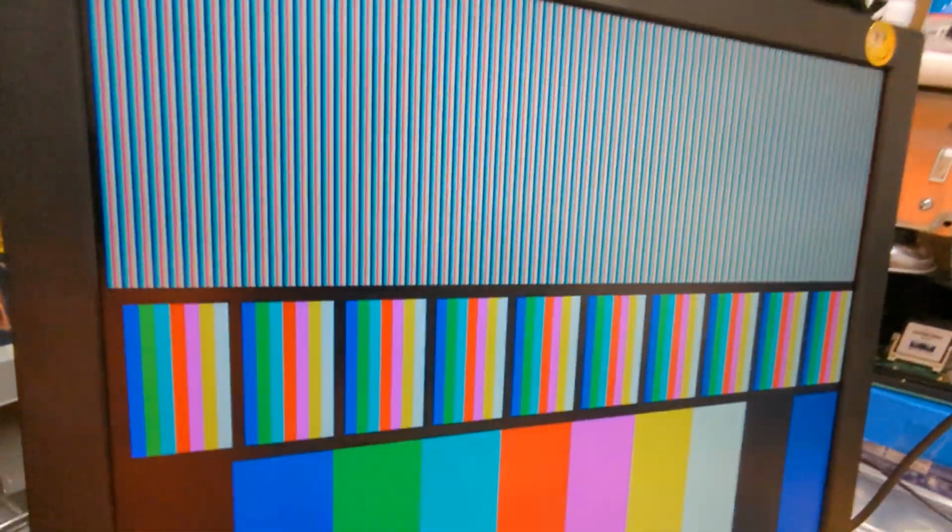This is the pattern I just described, and you can see these going really fast here. Now, this particular video monitor can go a higher resolution, so you can actually see multiple individual active matrix LCD elements. There's actually like 2 or 3 LEDs in there lighting up per pixel, because this can do 1024 by 768 native.